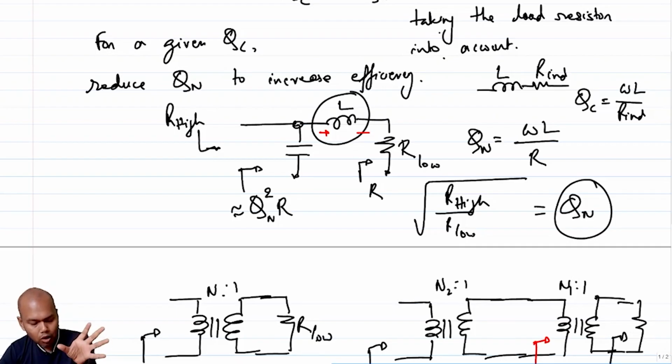So in other words, in order to get to high Q, you are depending on storing a lot of energy in your matching network, and part of the stored energy is delivered to the load. If the ratio of the stored energy to the energy delivered to the load is high, then you end up getting a high Q, and hence you get a high amount of impedance transformation, right? So the key thing to note is that in order to get a high amount of impedance transformation, you have to store a lot of energy in the matching network, correct?